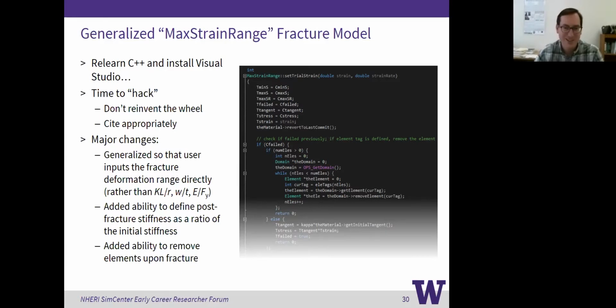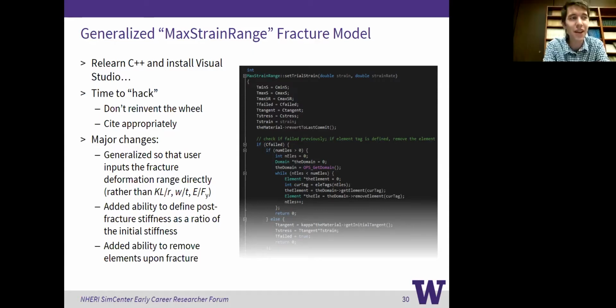So then another question is, how would you rate the convergence behavior of the proposed brace and connection model under large amplitude ground motions? It's generally okay. It certainly adds complexity to the model and lengthens the time it takes the model to run.